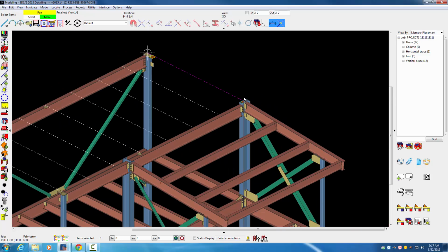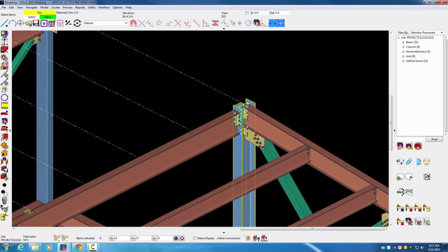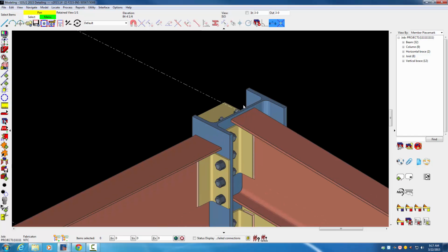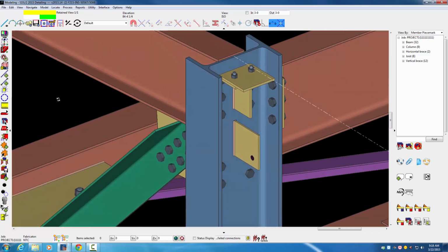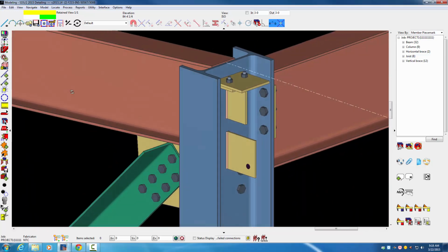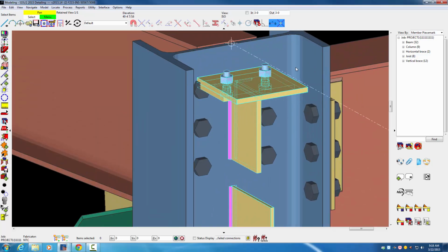So this is the bar joist on grid line 1 and B. So I'm going to zoom in here, and I'm going to show you a couple of things. First of all, let's zoom in and hold on your shift key. And again, if you hold on your shift key, your middle button will be the rotate. So hit down the middle button, rotate, and you can rotate around as you move your mouse here. And here's what the problem is.